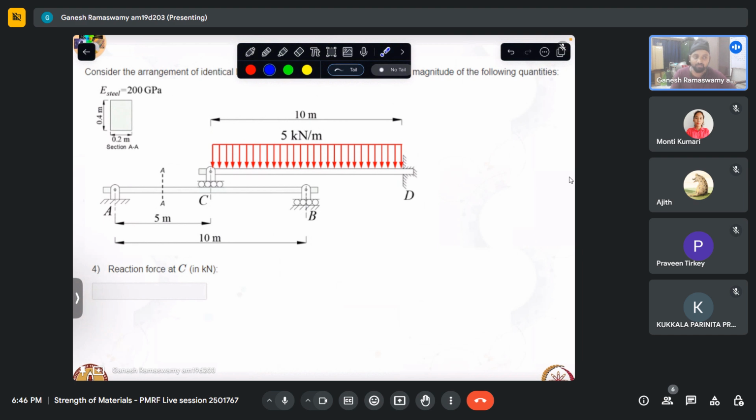But nonetheless, if one were to think about it, naturally this will move somewhere apart from the center, but still we push that under the rug, saying that we are dealing with small deformations. And we will actually see from the values that it is indeed a small deformation. Given the section and the length of the members, the deflections that come about at our points of interest are much smaller than the actual lateral dimensions of the members.